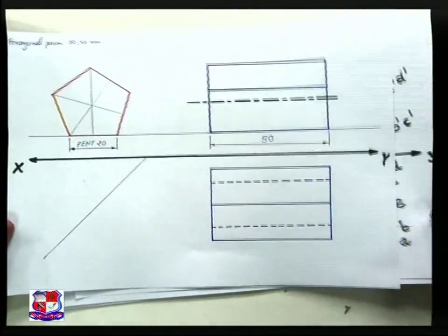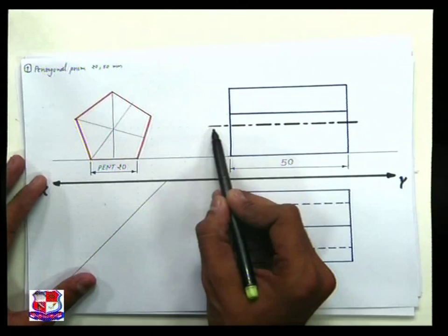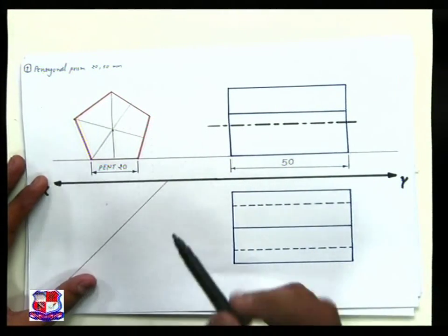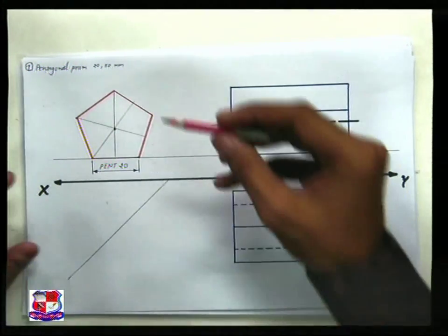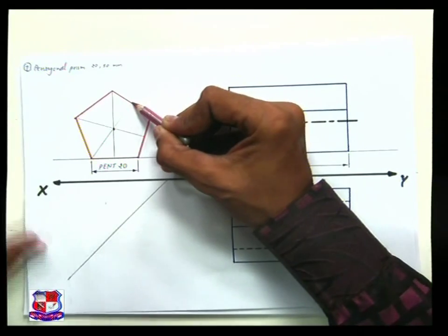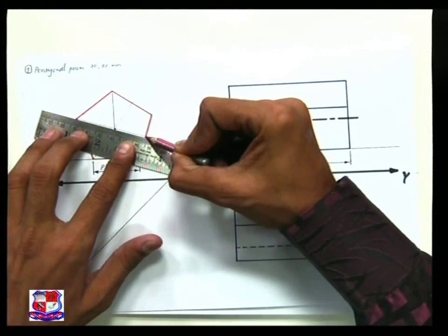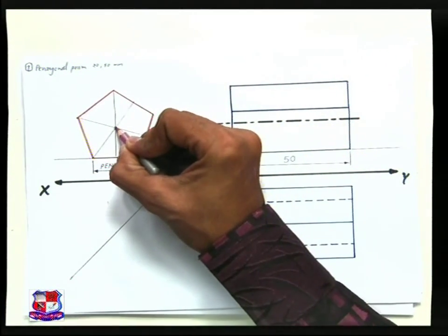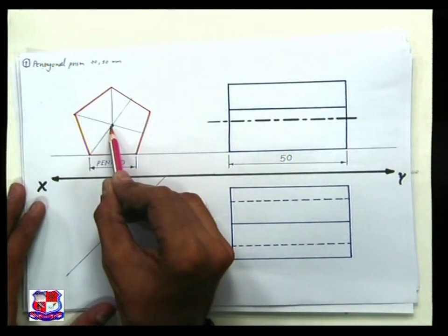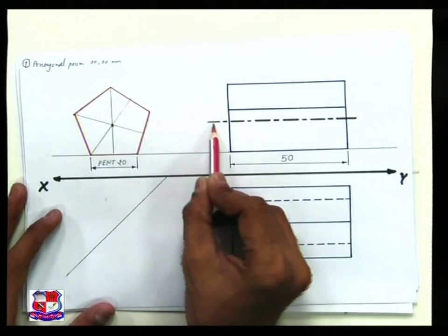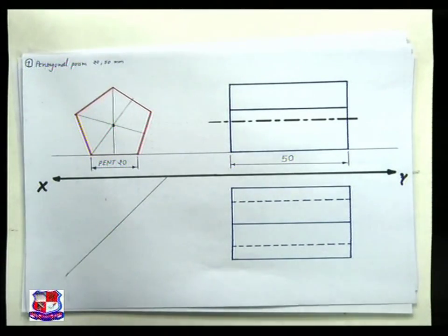You can draw the solution like this, in which you need to insert the center line, which is represented over here. This is the center line which is drawn from here. We know how to locate the midpoint of this pentagon. For that we have to find out midpoint of any side and join that midpoint with the opposite corner. Join midpoint of any other side to the opposite corner, and both these lines will intersect at one point, and that point is called the axis of this solid. So this is the axis of this solid. From this axis draw a horizontal line and mark here the center line of this solid as shown over here.